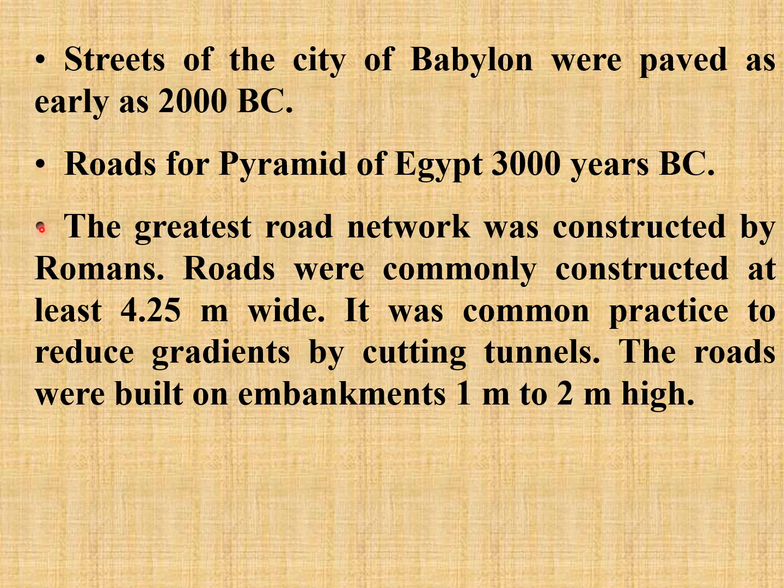Well, this point is very important. The greatest road network was constructed by Romans. Roads were commonly constructed at least 4.25 meter wide. It was common practice to reduce gradients by cutting tunnels. The roads were built on embankment 1 meter to 2 meter high.